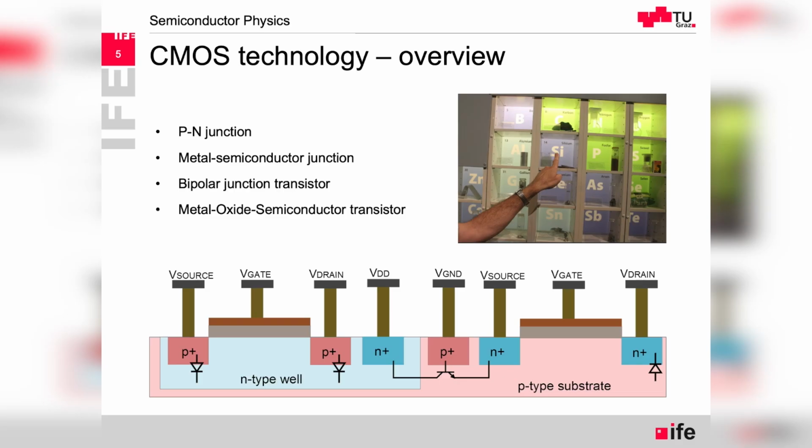The whole planar technology, which is CMOS, has the N-channel MOSFET integrated next to the P-channel MOSFET, creating this complementary pair where we can have circuits with very low power consumption, because basically the current between the power supply and the ground is, well, if we go to details and we have millions of inverters or logic gates, then of course it comes to a considerable power, especially during switching. But basically there is no static current consumption in such an inverter.